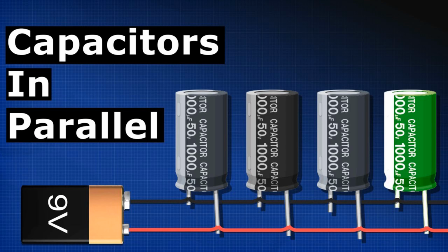Regulated power supplies. Description: capacitors work with voltage regulator ICs to maintain a steady output voltage despite variations in input voltage or load. Example: in a 7805 voltage regulator circuit, capacitors are used to filter and stabilize the 5V output, ensuring reliable operation for electronic devices.